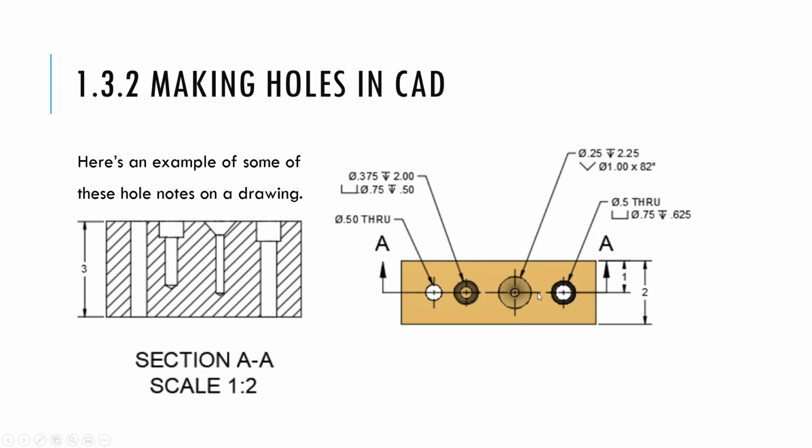So if I were to slice it and then flip it up and look at it from the front, I would see this is where the material's been cut. There's that 1/2 inch hole, it's a simple hole. Here's some more cut material in this area. Right there, that's our counterbore, and our countersink is this one. And then this is another counterbore hole, goes all the way through.